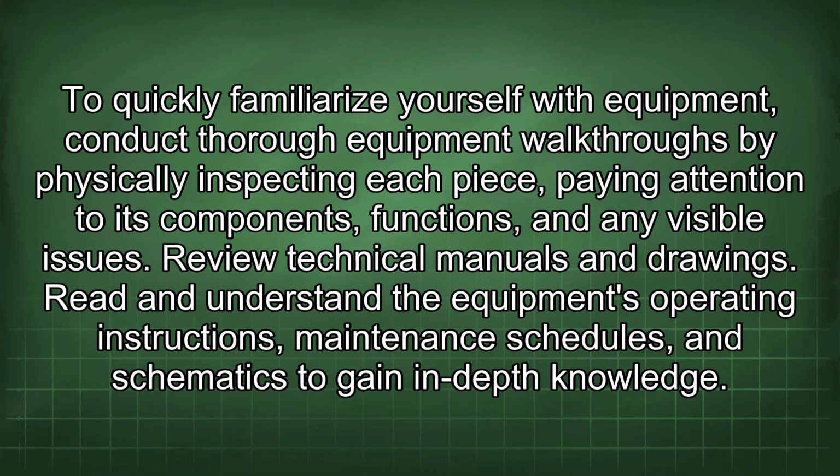To quickly familiarize yourself with equipment, conduct thorough equipment walkthroughs by physically inspecting each piece, paying attention to its components, functions, and any visible issues. Review technical manuals and drawings. Read and understand the equipment's operating instructions, maintenance schedules, and schematics to gain in-depth knowledge.